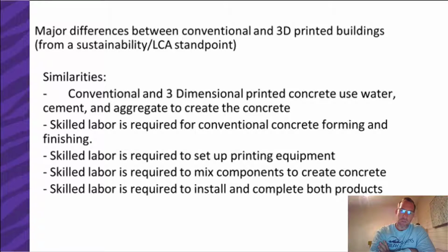Something to note with the skilled labor, you need the skilled labor to ensure that you're adding the right mixture, the right amount of fly ash, or the right amount of aggregate. Adding too much of one component over another changes the strength of the product, changes the slump of the product, so you're not going to meet the job specifications. So you need that skilled labor to understand what they're supposed to do in there.